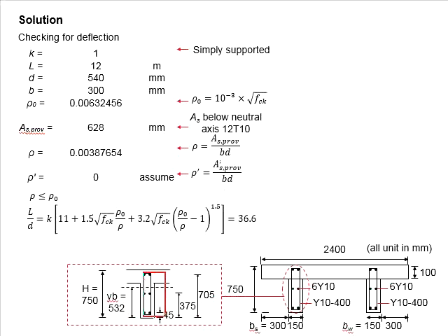This reinforcement bar not only provides resistance for the torsional moment, it also helps to control the crack for the partial prestressing, and it also provides resistance to the deflection of the beam. In total, there are 8 longitudinal reinforcement bars undergoing tension.